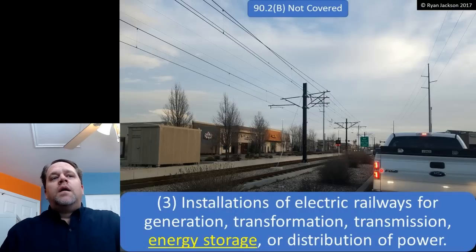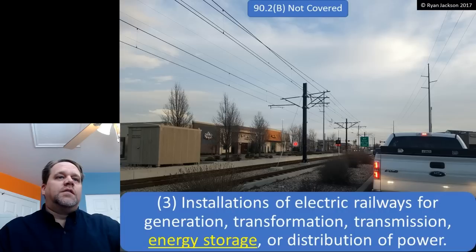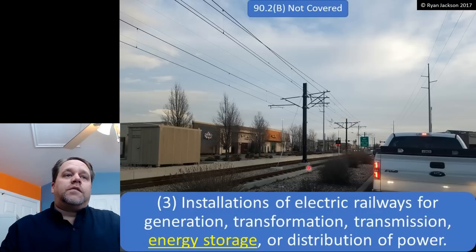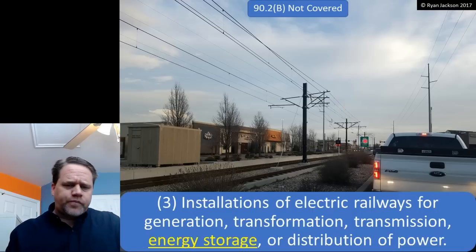Item 3, installations of electric railways for generation, transformation, transmission, energy storage, or distribution of power. All right, so here's an electric railway. This is in Salt Lake City, Utah. This is the TRAX system, and a lot of major cities, of course, have these. So you've got the train, and we know the train is not covered by the code, the rolling stock. And what this item is saying is that the wiring above is not covered by the NEC either.